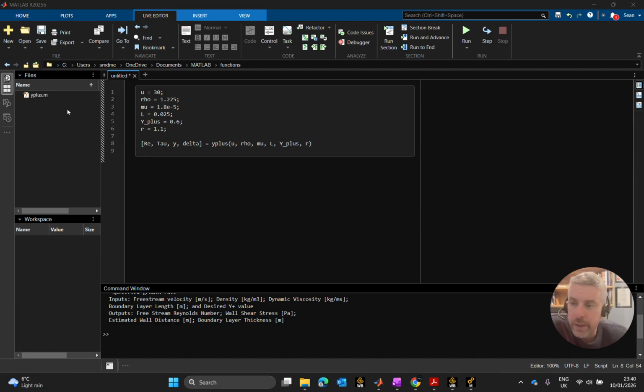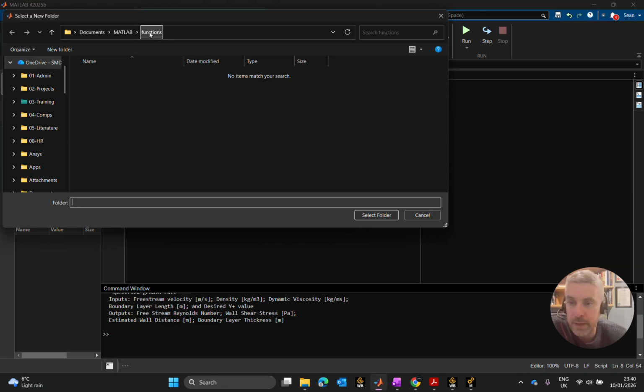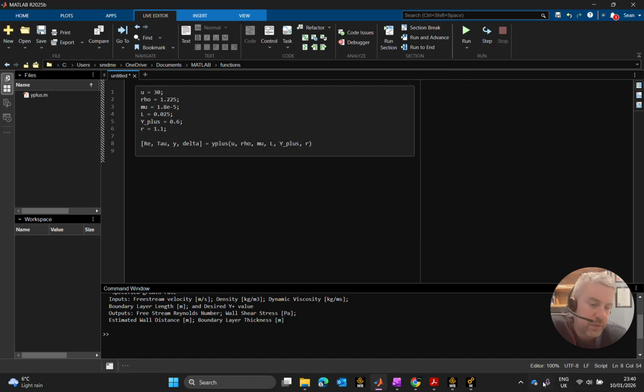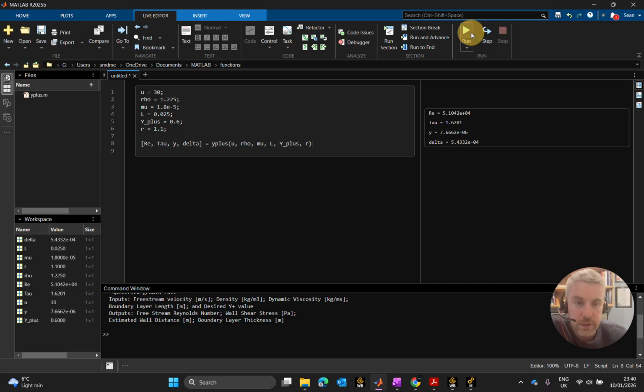All right, back again. Actually I took it out of the OneDrive folder and put it onto the documents folder. Documents, MATLAB, and functions straight onto my C drive, because I do have my OneDrive paused just to free up some bandwidth, so it's not reading it through. However, I'm now reading into that C directory, so when I run this now, I absolutely can get out my values. I can see my Reynolds number for this is just over 51,000 when I'm running a velocity of 30 meters per second. My wall shear stress is 1.62 pascals, and that there is the height of my first cell